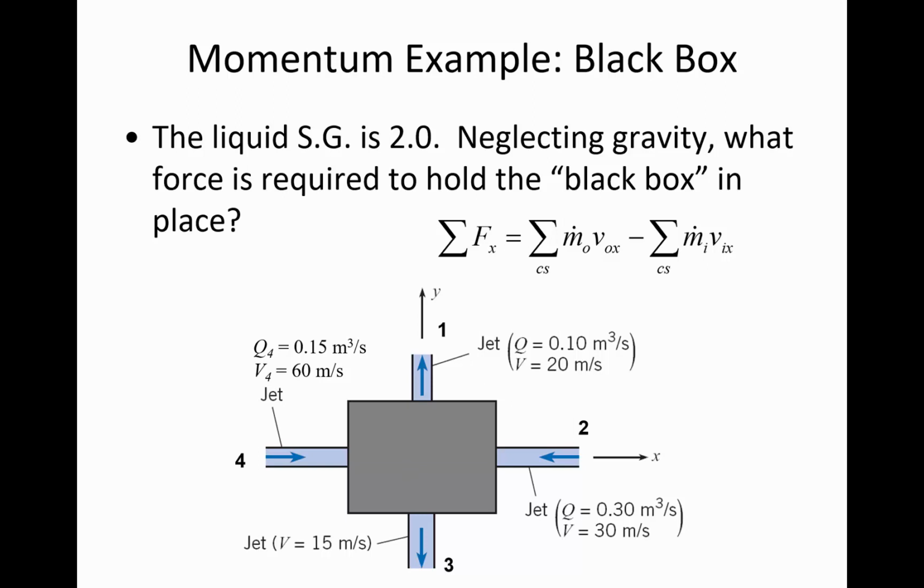All right, so I'm going to pause again for a second, and that will give you some time to calculate what is the mass flow rate at 3 in terms of kilograms per second. And then finally, what is the force required to hold the system steady? Remember that we want to know the force and also the direction. So do we need to apply a force up or down to hold this steady when it comes to the vertical forces that are necessary to hold the system steady?